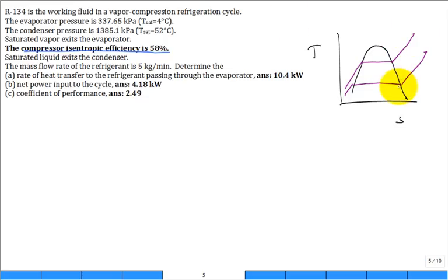I'm still coming out saturated vapor state 1. I put it through the compressor. If it was a perfect compressor, it would be 2S. But where is 2 actual now? It's even going to be worse. A higher temperature to the right, because you have to increase in entropy because of entropy production irreversibilities. So maybe you're out there and you can solve that problem. It's just 2 steps to go from state 1 to state 2. That's 2S, and then it's 2 actual.